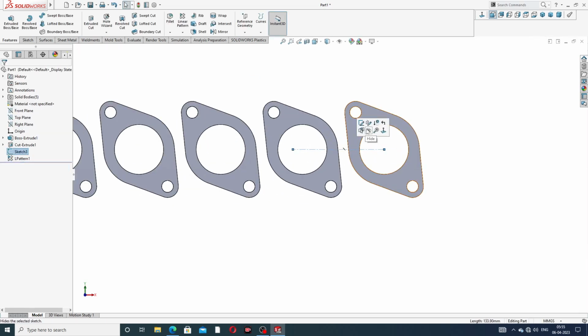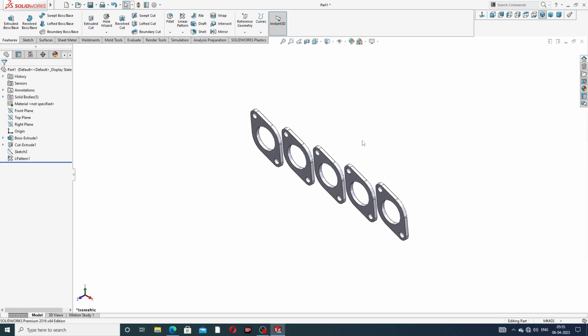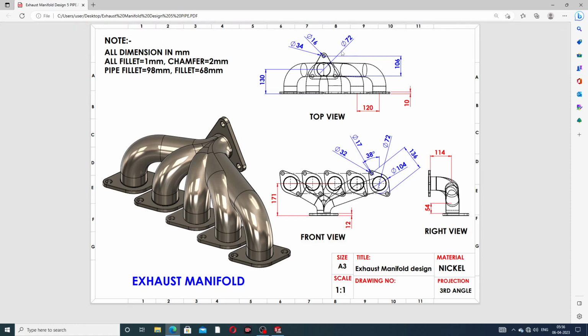And this is the height, because this board is looking perfect in isometric view. Okay, and next, use this distance of 171 millimeter, and draw this body, and the distance between is 130 millimeter, and this distance is 106 millimeter, and this big circle cutout is 72 millimeter, and a small circle is 16 millimeter, and this big circle is 34 millimeter.